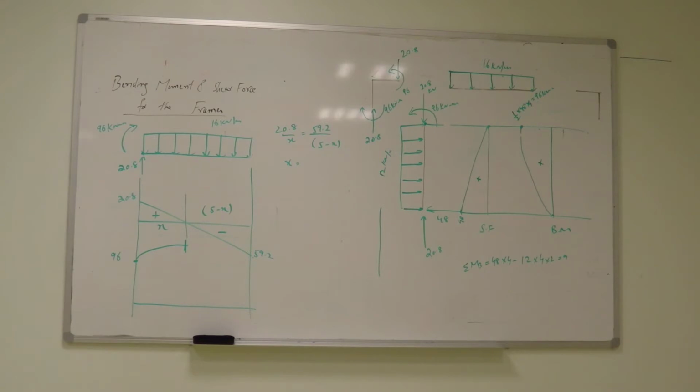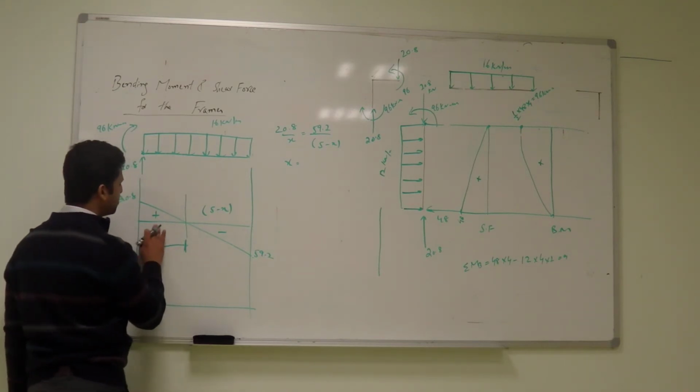We know that the shear force is 0 at that point. So write the equation for shear and put it equal to 0. 4.3? Total is 5. How can it be 4.3? It's definitely less than half. So x is 1.3 meter.